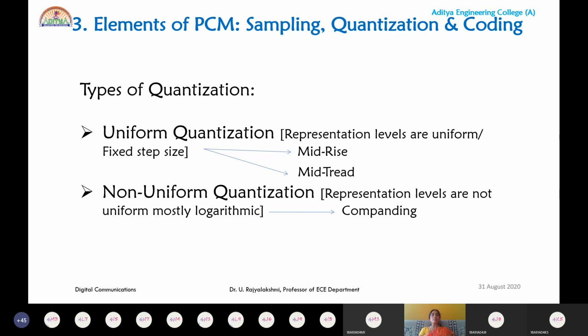If the origin lies in the rising position of the step, it is called mid-rise. If the origin lies in the tread position of the step, it is called mid-tread uniform quantization.